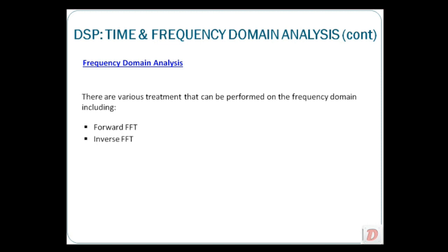Only in the frequency domain can you see what frequency components you do not want, so from there you can filter them, remove them, then transform back to a cleaner time series signal. That's through inverse FFT.